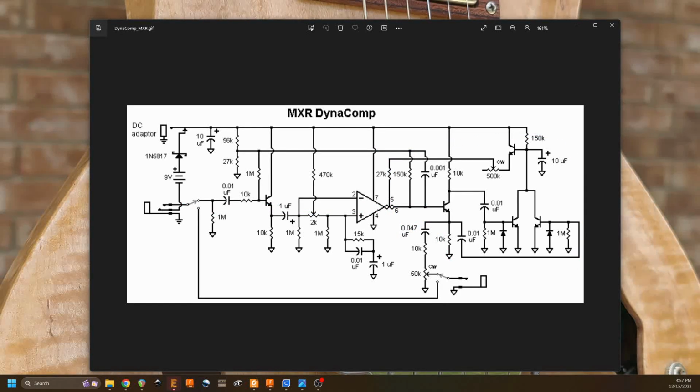If we were to have a feed-forward envelope follower, we would tap it off right here, and we would have our envelope follower circuitry here that would then control our amplifier, so that if there's a big transient in here, then right about the time that the transient gets to our amplifier stage, it's also going to receive a control signal saying, hey, turn the signal down, reduce your gain.